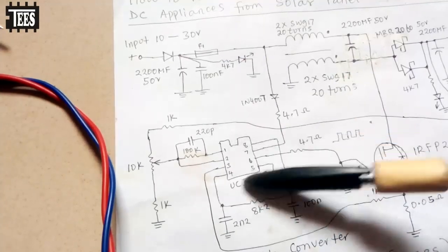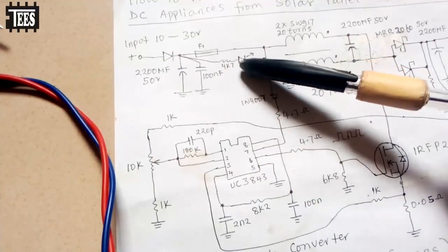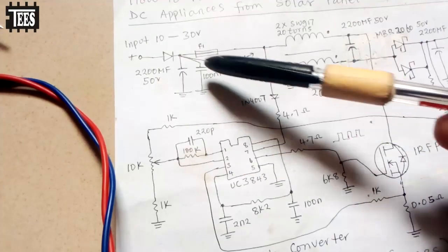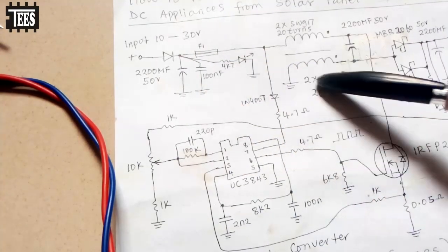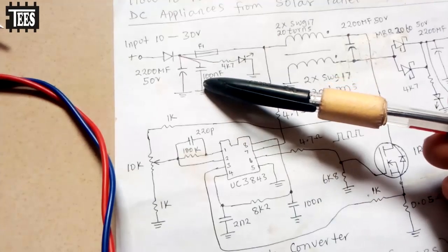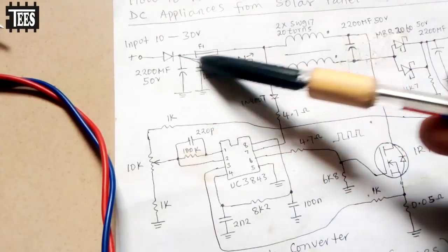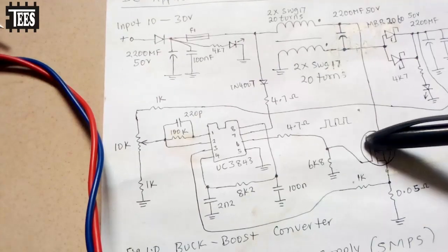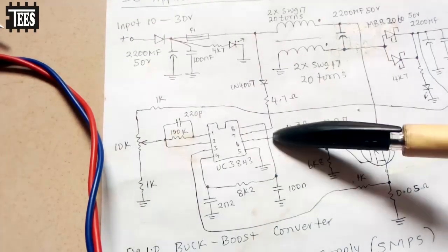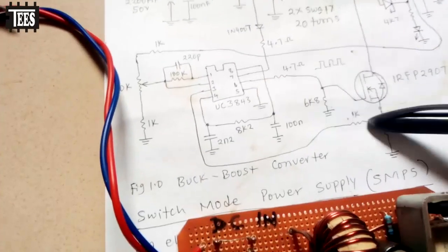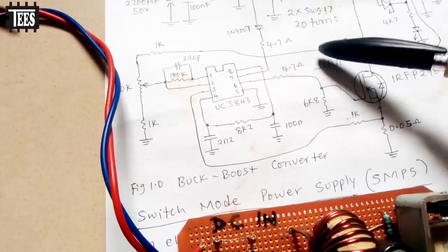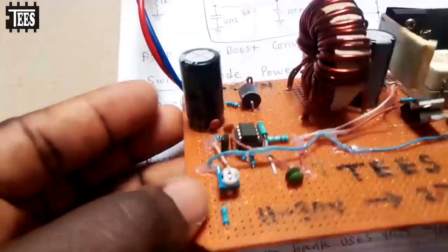Based on this IC here, the maximum input voltage is 30 volts. So that's the range this thing operates. For this thing to be able to regulate properly, the input voltage should be around 10 volts. So if I have 10 volts, I can get 30 volts here, or adjust to any voltage within that range. This particular part is for current sensing, while this one is going to sense the output voltage. So that's how the entire system works.